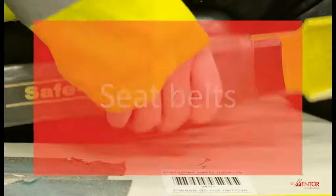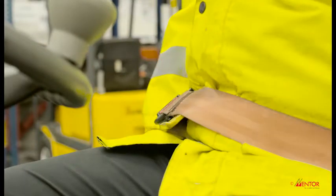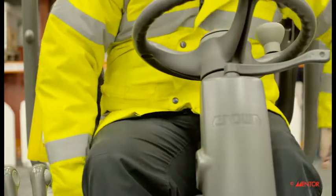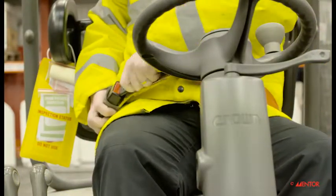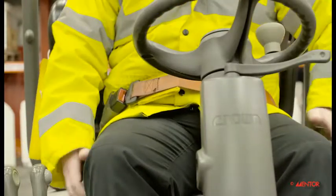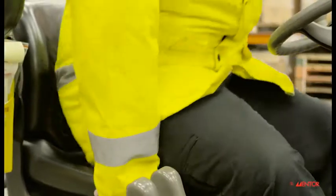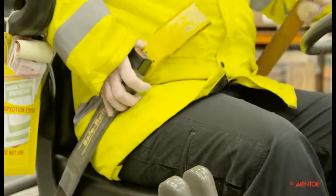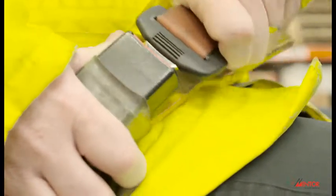The law requires that a seatbelt must be worn whilst operating a counterbalance, pivot steer, telescopic handler or side loader with a lifting capacity of under 10,000 kg. For all other types of lift truck, if a seatbelt is fitted, then it is advisable to wear it, and if it is your company policy, then you must wear it. The only exception is if a very specific risk assessment has been performed under HSE Guidance Note MISC 241.